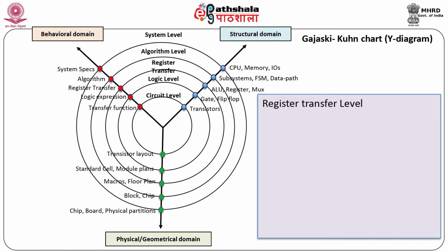Instead of using continuous values, if the signal's voltage is above or below a threshold, then it can be interpreted as logic 1 or logic 0 respectively. In addition to binary values, the input output behavior is described by Boolean equations. The abstraction converts a continuous system to a discrete time system and helps to discard the complex differential equations. Similarly, propagation delay is used to specify the timing of a gate.